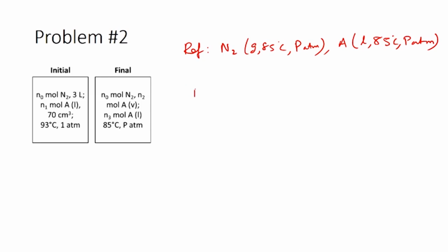So, the components would be nitrogen, component A as liquid phase and component A as vapor phase. As I had already mentioned, we should always list out components of different phases separately while we are writing these enthalpy or internal energy tables for phase change operations. In this table you have N initial and U cap initial. So, instead of enthalpy we are using internal energy, and you have N final and U cap final, which would be the specific internal energy for the final condition.